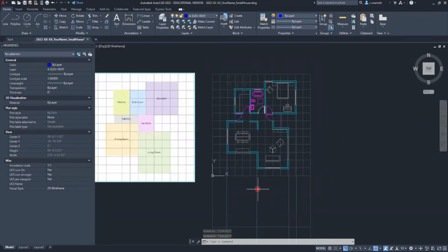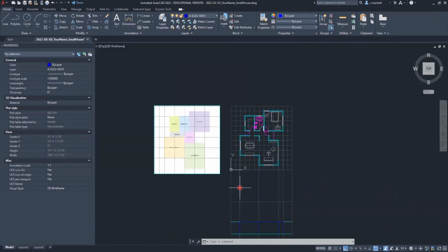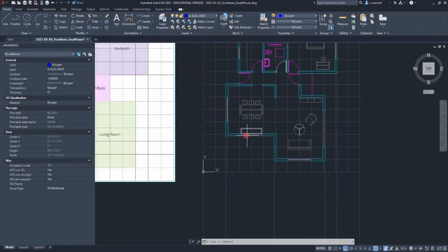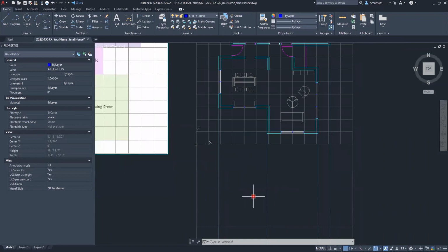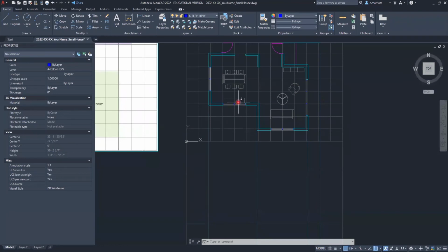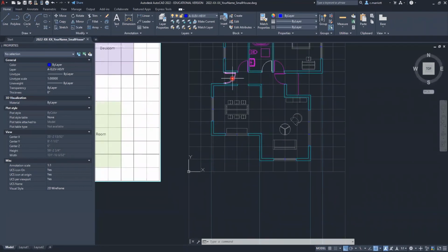Now in my elevation, I also have some windows drawn, and we haven't really talked about what these windows maybe look like. You could draw a rather standard window, which might start about 3 feet above the ground and go maybe up to 7 feet. Sometimes the tops of windows align with the typical height of a door, so that when you look at the elevation, the top of the window is at the same height as the top of the door. It just gives a little orderly, consistent look. For residential projects, doors are typically going to be 6 feet 8 inches or 7 feet. Probably 6 feet 8 is more common.